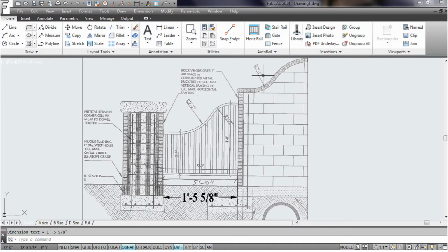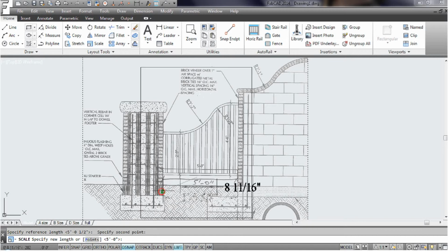All right, easy enough to do. So what we'll do is we'll use the scale command. I'm going to select the PDF and the dimension. Right click, base point anywhere. Then I'm going to click on reference, or I could type R for reference. And the reference length, we want to make the reference length the dimension lines, which I've midpoint here and midpoint there.